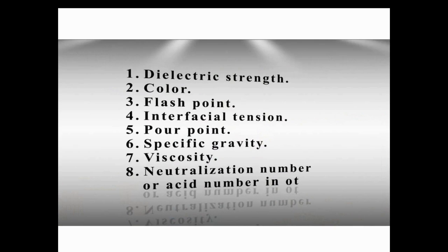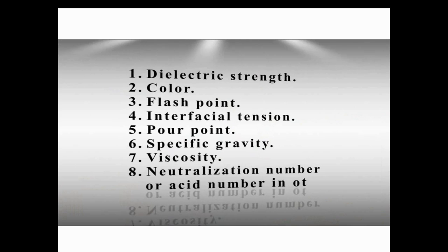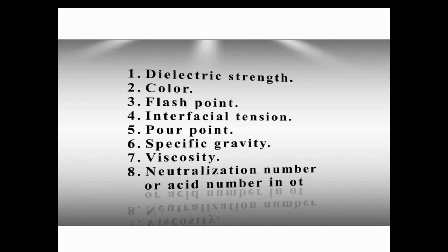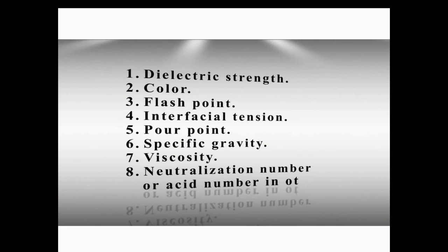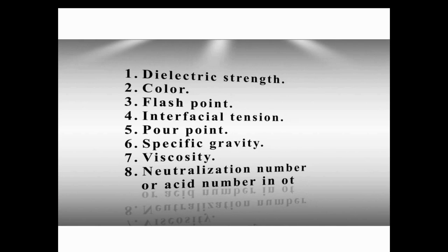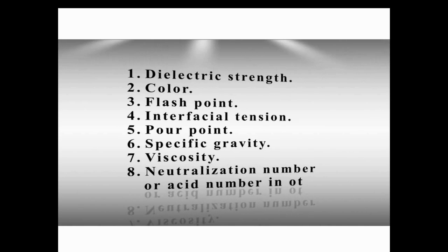When it comes to purchase, oil draws the most attention to the following specifications: dielectric strength, color, flash point, interfacial tension, pour point, specific gravity, viscosity, neutralization number, or acid number, in other words.